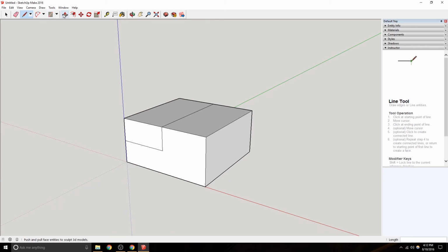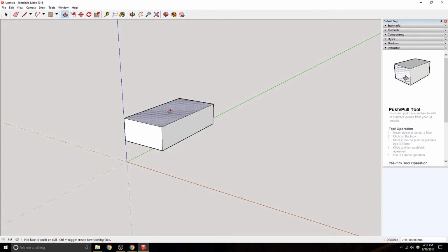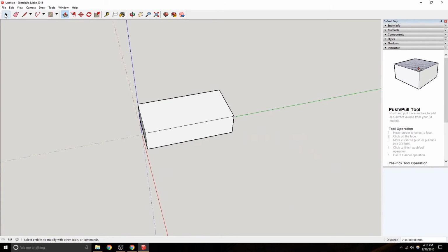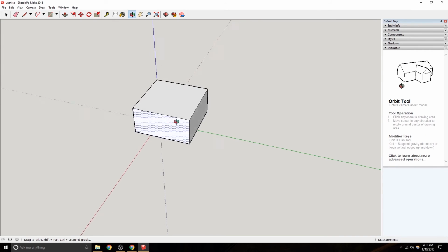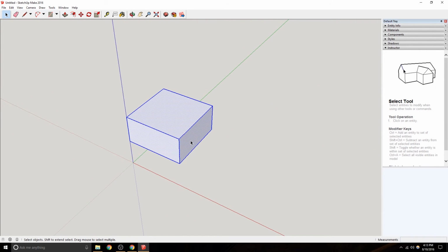And then the extrude also works in the negative, so you could remove a piece of the puzzle. Check the back side, make sure it didn't disappear. You can also, let's cut this in half again, take this down to 50. No, I'm sorry, Control Z. It's 200 total length, so cut it in half, it would be 100. Alright. So now we got this block. You can select the whole thing. You can right click. You can say make group.